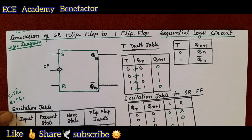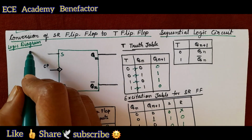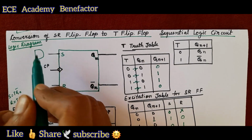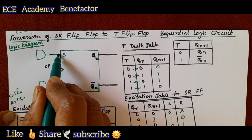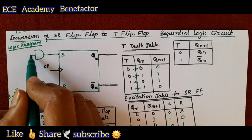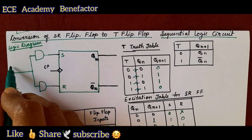So we need two AND gates, one at S, another at R. So let us put two AND gates here, like this. Now to both these AND gates we can give one common T input.